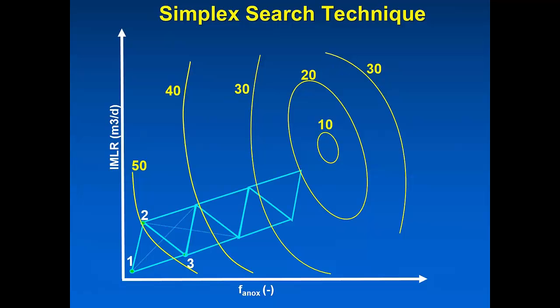And basically, as it keeps running and replacing points, eventually it gets to a point where that guess was maybe not actually the best guess. If we went one too far, this guess over here is actually worse than this one. So what it does is it backs up, it contracts, it then continues on its process of finding new places and contracting and flipping and reflecting through each point until it finally gets to a point which it knows to be the best job that it can do. It can no longer minimize effluent total nitrogen anymore. So that's what it looks like in a theoretical sense.